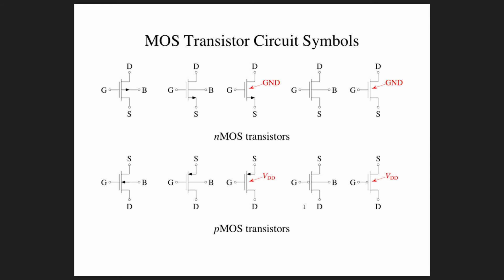And in the schematics that we will be drawing and working with this semester, we will be following a particular convention. So when we don't show a 4th terminal and resort to a 3-terminal MOSFET, we have a default assumption for that 4th terminal connection. For an NMOS transistor, that default will be that it's connected to the most negative power supply voltage, which is for us ground.